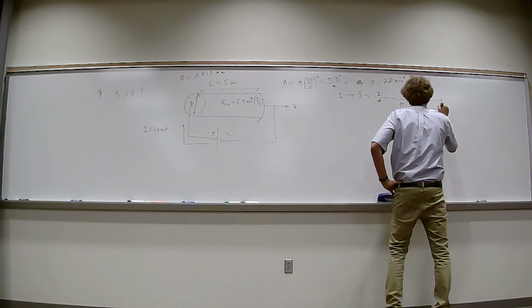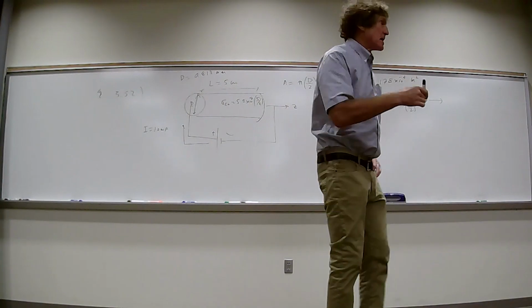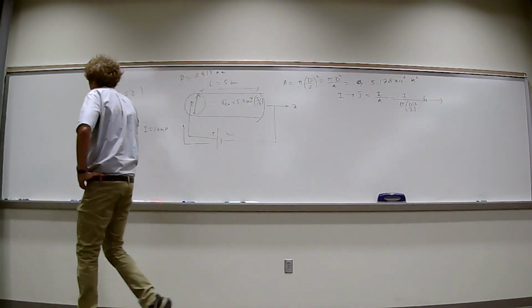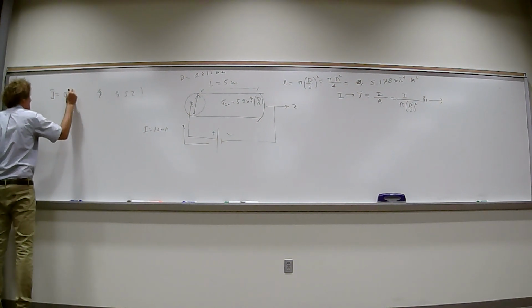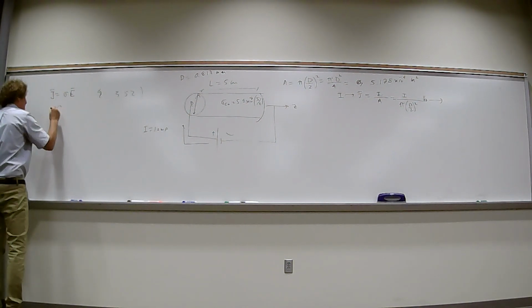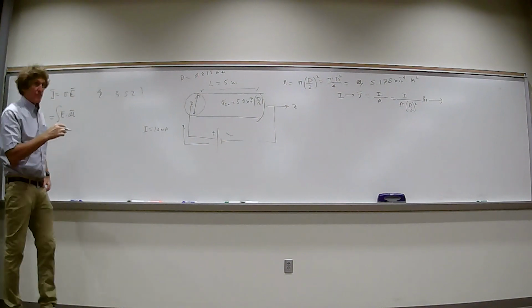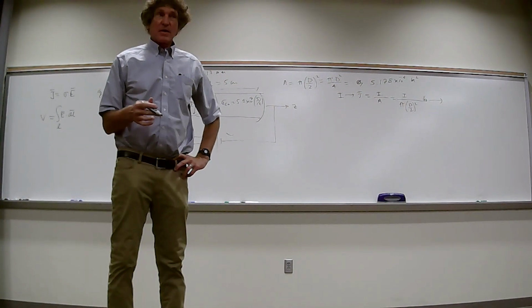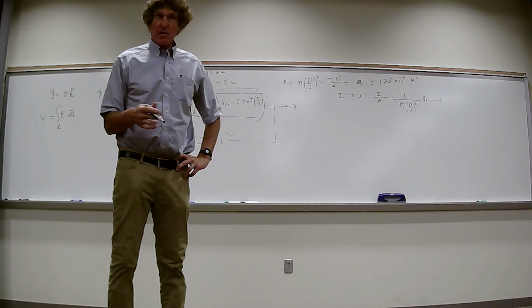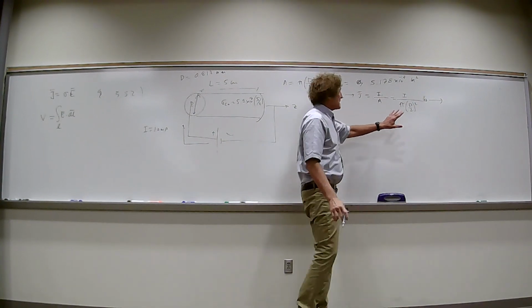What's my next step? You remember? That's current density. After I have that, what do I get? That's J. Remember this always. J is equal to sigma E, right? And we know the integral of E dot dl over the length of the wire is the voltage. We're going after the voltage. If we have the voltage in terms of the current, then we have the resistance. Do y'all follow? The logic is clear. So we've got this. I'm not even going to be bothered putting in the value for D here.